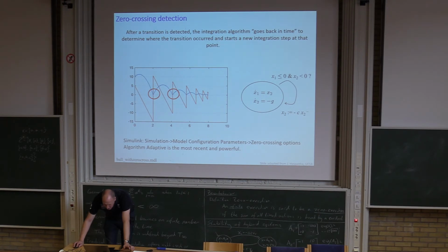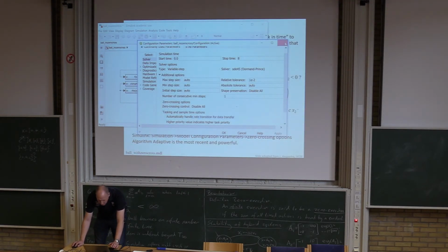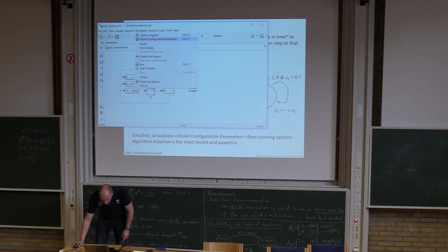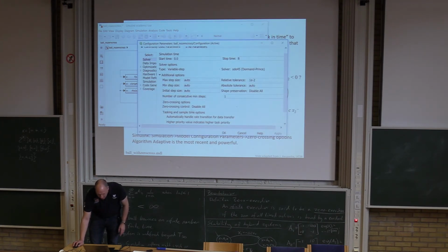We go into simulation and model configuration parameters, and then you need to have this zero crossing control here.